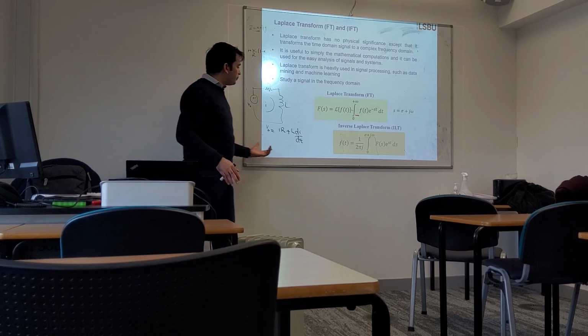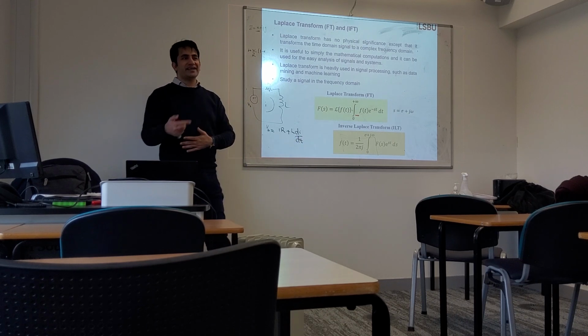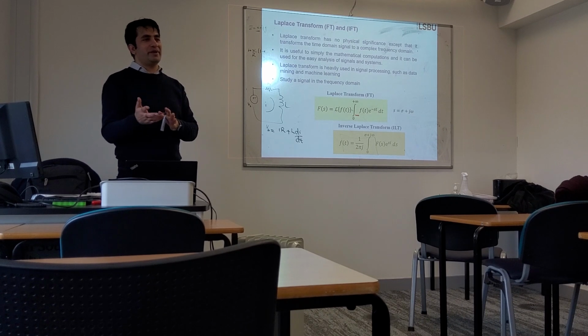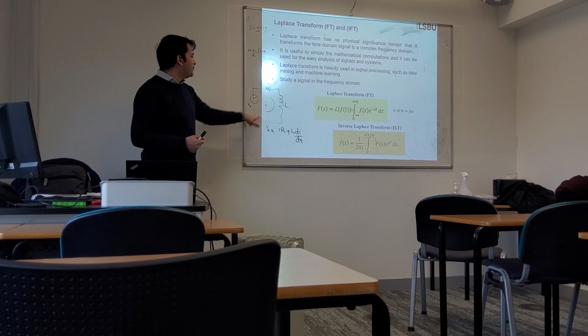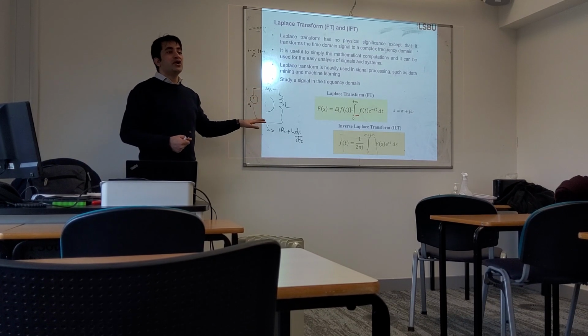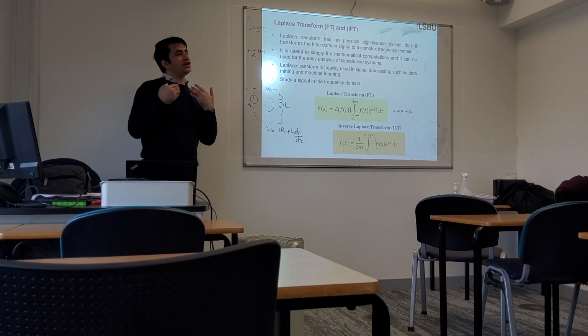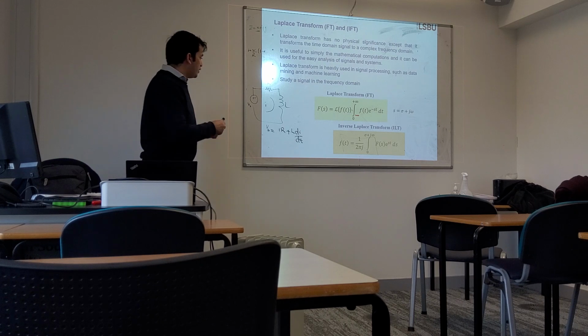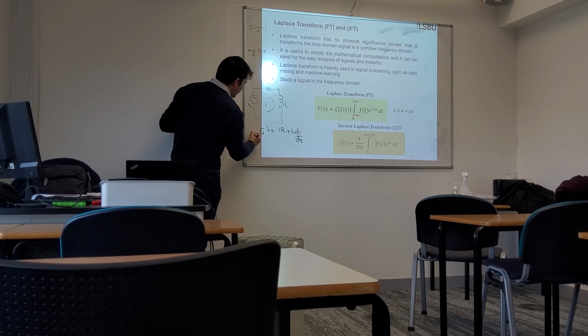So what we do, we normally apply the Laplace transform, we find the current, but since we don't want our final current in Laplace domain, because we want to see it in time domain, because we want to analyze our circuit in time, after applying Laplace for our simplicity and solving it, we need to take the inverse Laplace transform. So how do we solve this? We apply the Laplace transform.